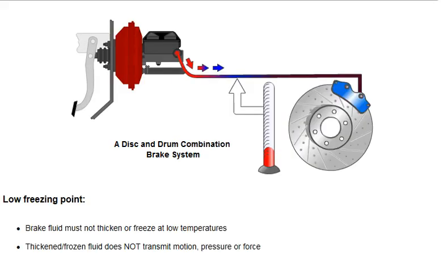The brake fluid must have a low freezing point. If the brake fluid thickens when it's exposed to cold temperatures, it will not transmit the pressure from the brake pedal properly, and the brakes will not function as intended.